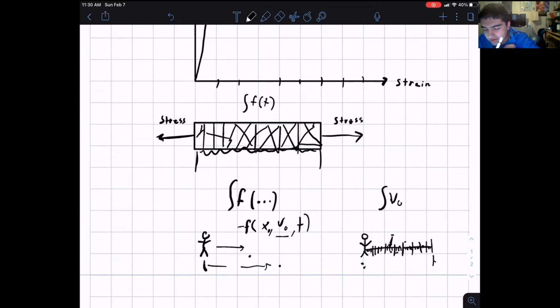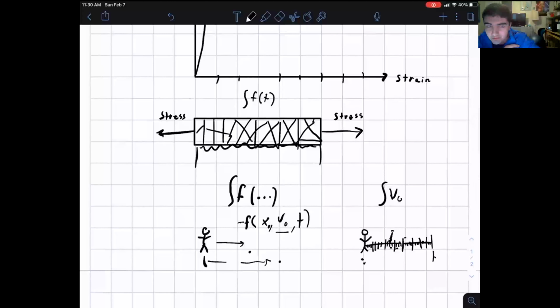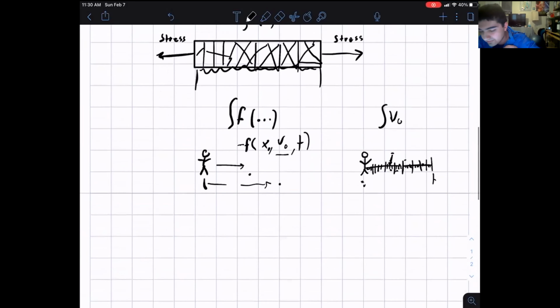So see, now this is broken up into, I'd probably say, 20 or 30 different components. And that's going to give you more or less a pretty good approximation of how this item will behave under stress. And it will give you the von Mises analysis of all of these elements. These individual things are called elements. What is von Mises? Well, von Mises is essentially going to tell you what areas are experiencing the most amount of strain as a result of this process. It's going to tell you what areas are experiencing the brunt of this stress in layman's terms.